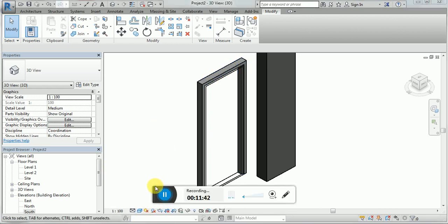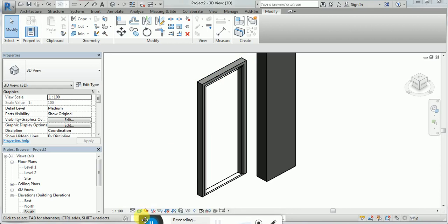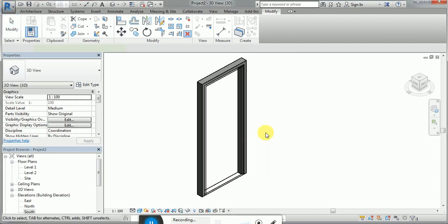Till now, you have seen the extrusion command as well as the sweep command. The difference was, in extrusion, you can extrude the profile along a single direction, whereas in the sweep command, you can extrude it in multi-direction. Now, I can create a pipe using this command also.